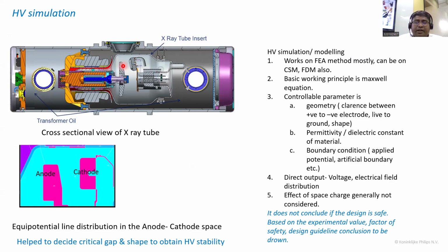So if you have a bigger size of what we call in our terminology the focal spot from which X-ray emits, you have more probability of image artifact effect. And hence they need it very small, high voltage needs it very big. And here comes a design compromise, optimizing both the requirements so that both functional requirements are met. So for this high voltage, we again use some numerical tools to optimize, and based on the guideline established internally, we set the distance between these two.